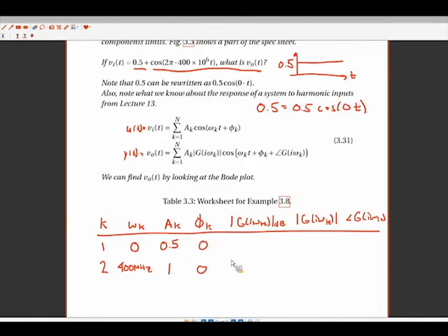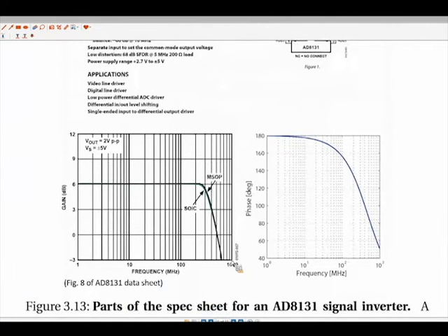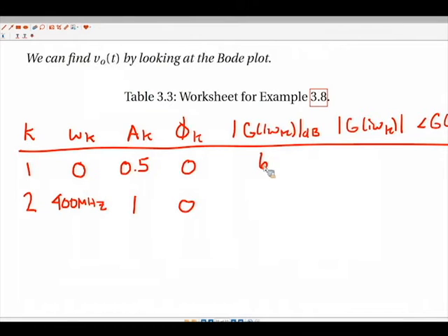All right, so now on to the Bode plot. The rest of this we have to fill in from the plot. So first we're going to look at what is the magnitude in decibels at a frequency of 0? A frequency of 0 does not exist on a Bode plot, right? A Bode plot is given a log scale, so that would be 10 to the negative infinity. That doesn't exist. But we know from your work in hand plotting Bode plots that they asymptotically continue if they're off the chart, you just take the asymptote and keep on going. In this case, a frequency of 0 is way, way, way over here, all the way in Worthington, North Columbus. So we're just going to assume that this is flatlined here, and it's going to continue on at 6 decibels. That's how we would read this. So we'd fill in here that the magnitude in decibels is 6.